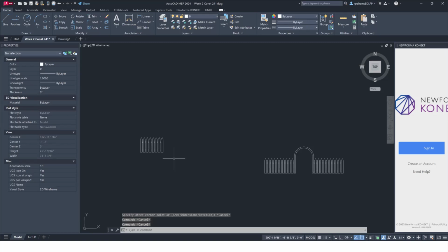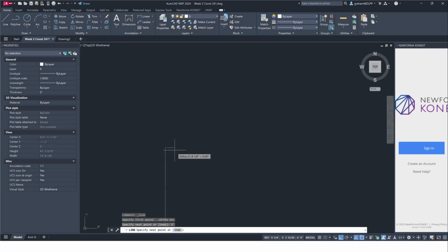Yeah, that wasn't cool. So I don't know why it's being a pain, but when in doubt, you can always come back to a tool you use that can work correctly, and we can draw this thing. Just draw it 5 feet up, another line 1 inch over, and another line 5 feet down, and another line over. So sometimes drawing 4 lines is easier than drawing a rectangle just because of the way the parameters work. Okay.